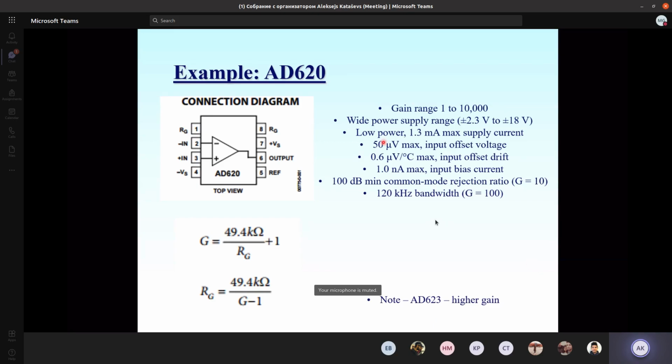If you look at this amplifier, we have the general inputs: here we have a power supply, plus supply voltage and minus supply voltage. The amplifier typically works with a bipolar power supply, so we need to apply minus and plus, but this particular one may work with a single power supply too, from 0 to plus 5 volts.